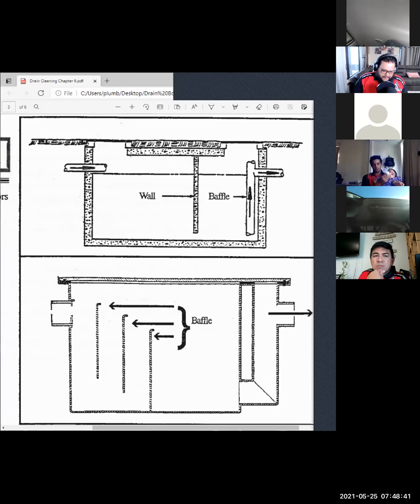Know your distance. Like Steve talked about, the mantle, the crust layer of the grease in that grease trap. I think they were saying 30% they can be safe with their grease in that trap. That mantle can be at least 30%. That's about correct, Josh. So if you had a 5-foot deep one and you're 2 feet deep, you're right there. Yeah, so they can be at 30% and still be okay. But you'd really be able to feel grease if you were poking all the way through it.